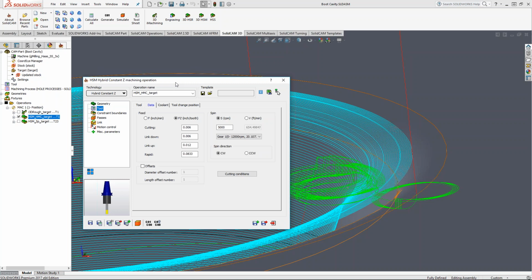So to maintain a consistent cusp height both ways, as far as the step over and also the step into the tool path, that general rule was like half of the step over would give you pretty much the same finish for your inch per tooth, for your feed Z here.